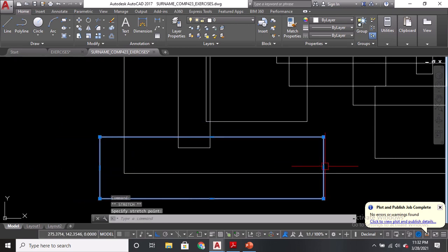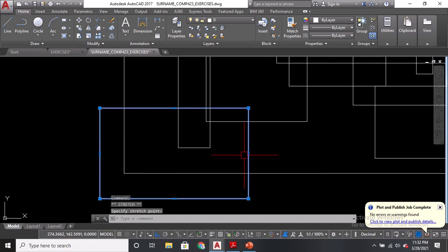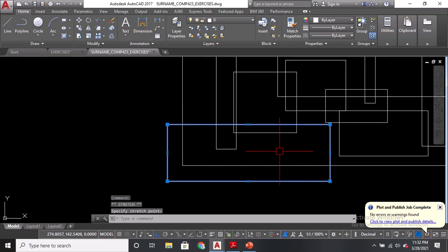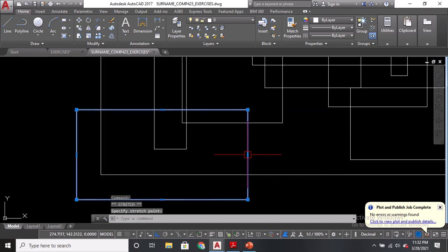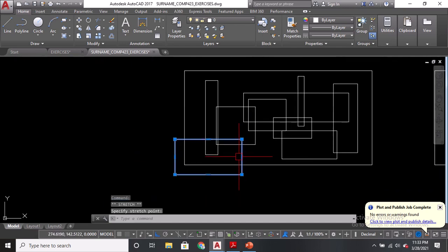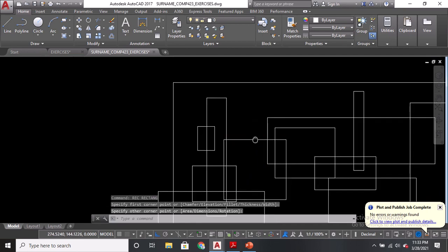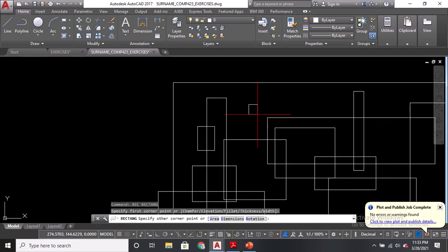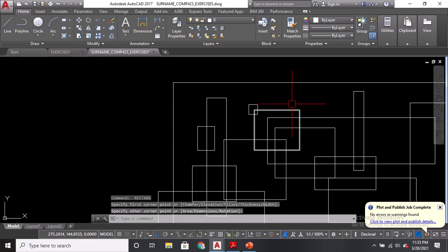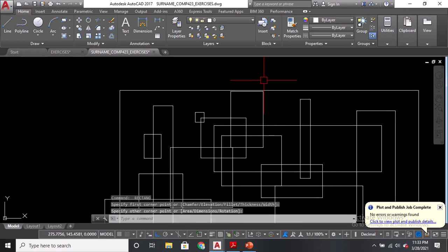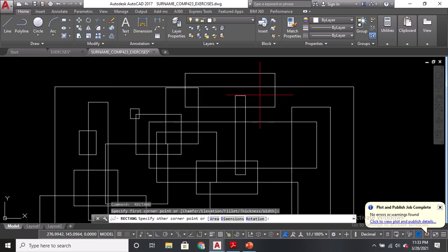More of rectangle modifications as we go along. So, for the meantime, middle grip muna yung pakialaman natin. Okay? So, there you go. Escape ko lang. Okay. So, that's another REC. You can have smaller ones. That's 1 and 2. REC, enter. 1 and 2. REC, enter. 1 and 2. Or enter to repeat the previous command, which was rectangle. Pwede kayo lumagpas. We can easily trim that later.